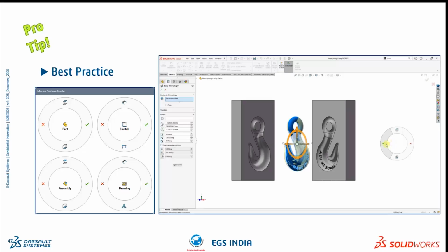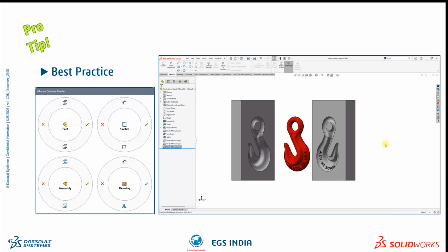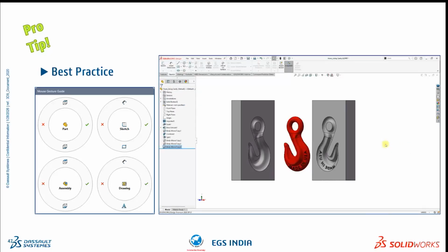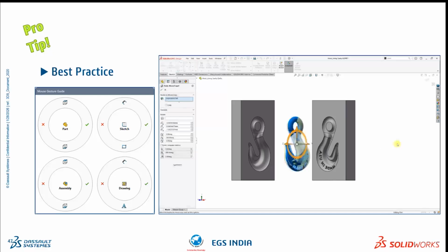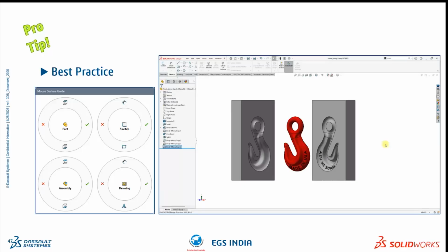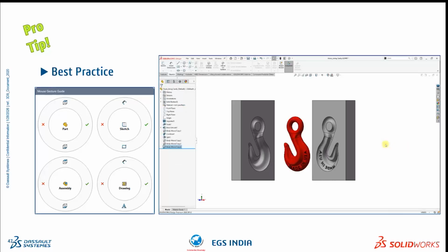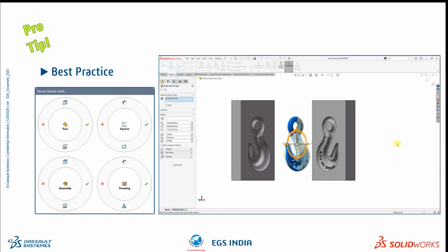Our pro tip for using the mouse is to dedicate the horizontal right and left options to the most frequently used commands. In this case, we are using horizontal right as the OK command and horizontal left as the cancel command. The rest of the 10 out of 12 options can be customized in your design workflow. By following these pro tips, we further restrict our cursor movement in the graphics area, reducing both the time and effort to complete your design.